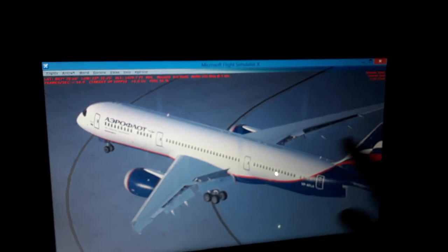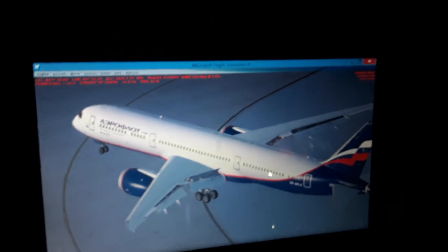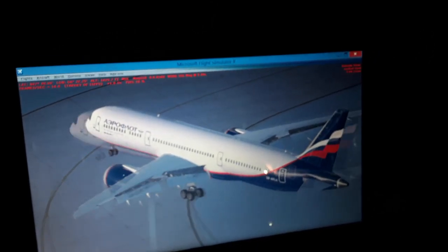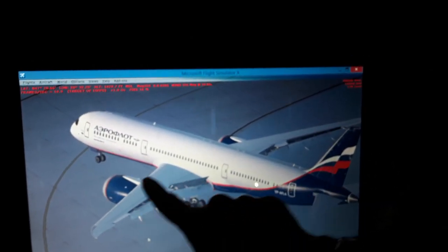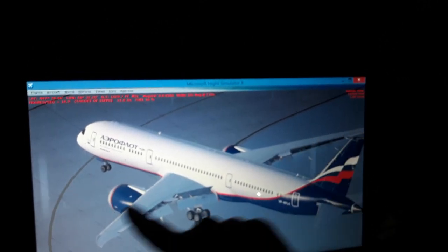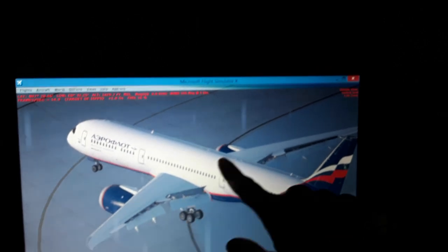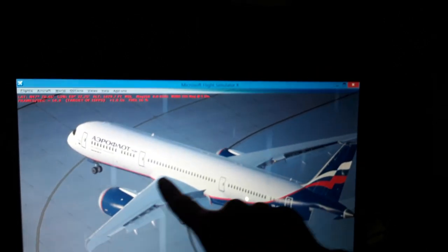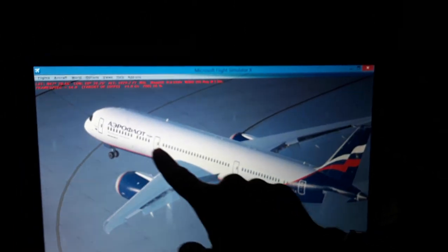the wings hold the aircraft weight as we fly. We have the thrust from the engines that push the aircraft forward, the vectors from the thrust from the engines, and we have the lateral axis from wingtip to wingtip. The mean aerodynamic chord position, about 23% of the MAC that I told you, is pretty much here where the maximum aerodynamic lift occurs, and also where the stall will begin, the top surface of the wings. As we fly, we have the center of gravity transverses through here approximately. We have the longitudinal axis from nose to tail that affects also the roll action.